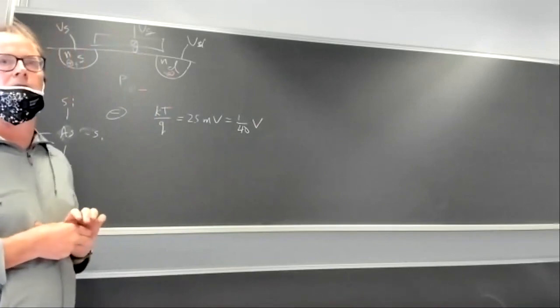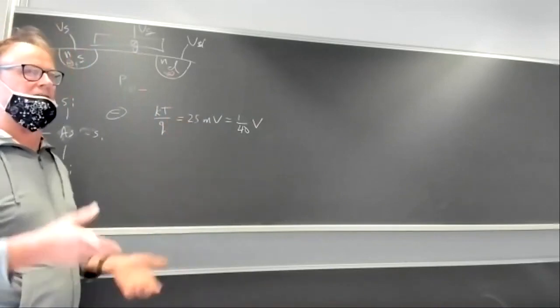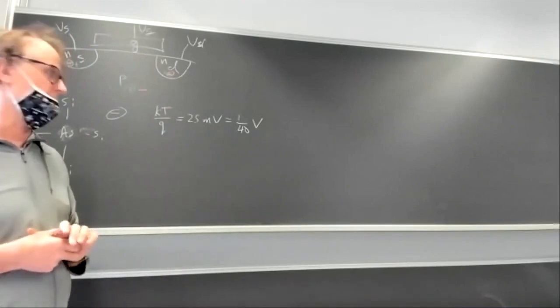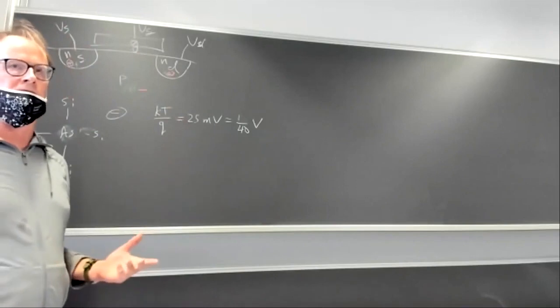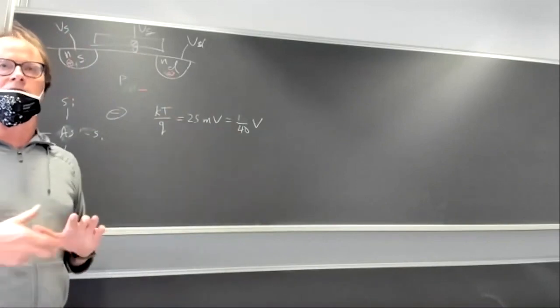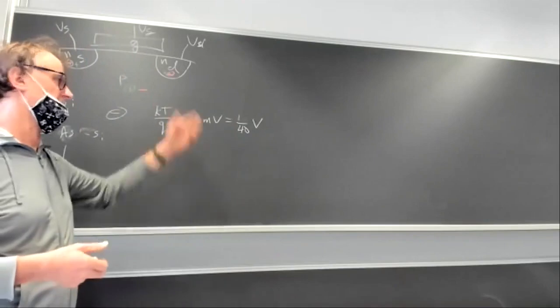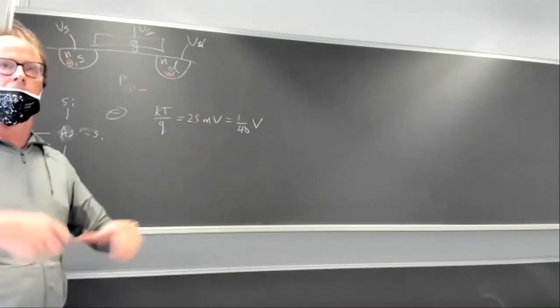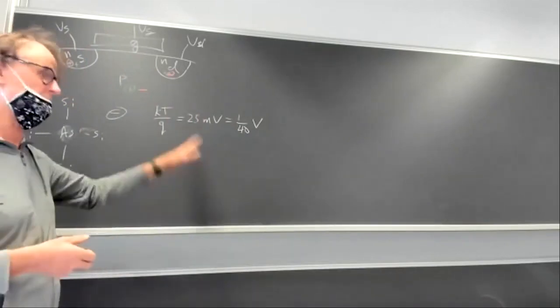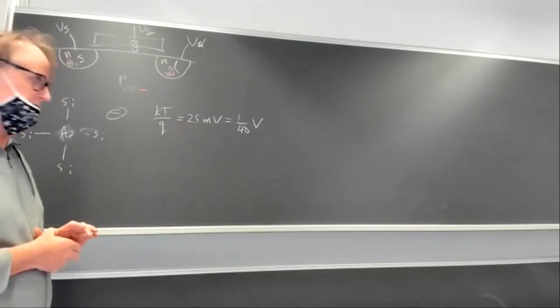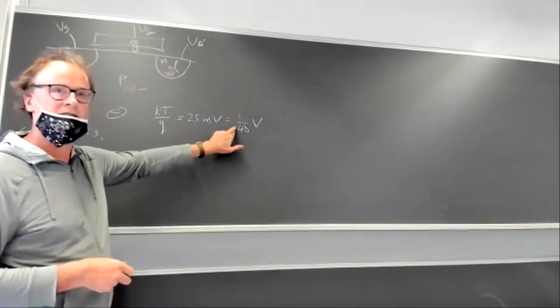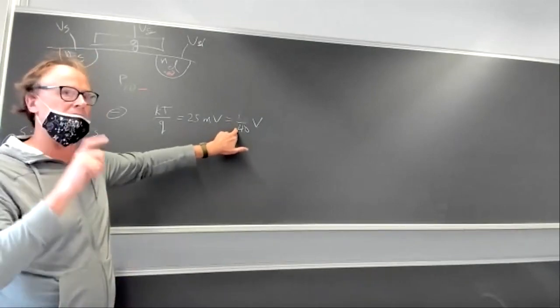Yeah, room temperature, roughly. It doesn't vary that much in normal transistor operation. You go from minus 40 degrees up to like 100 degrees. Compared to 300 degrees, that's not a big change. It varies maybe a factor of 2 at most over the whole range that people use normal transistors. So it's always a tiny fraction of a volt.